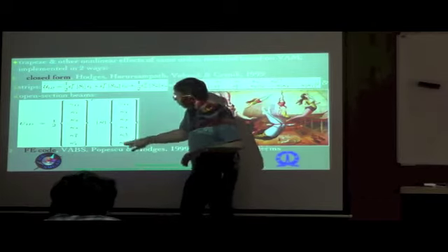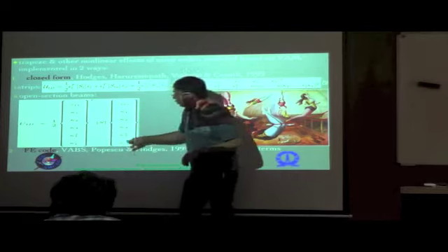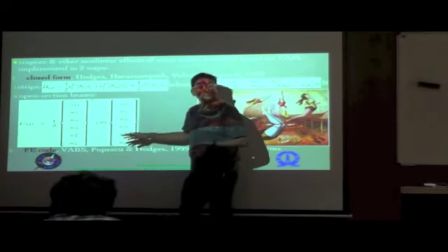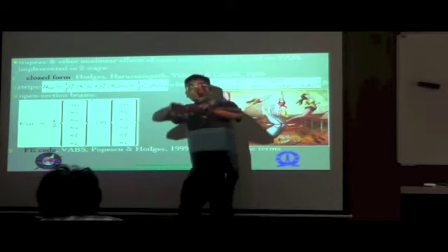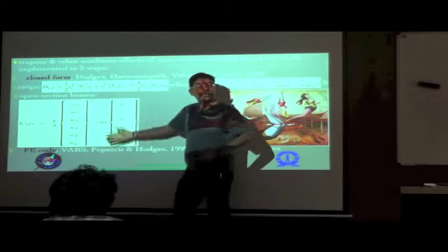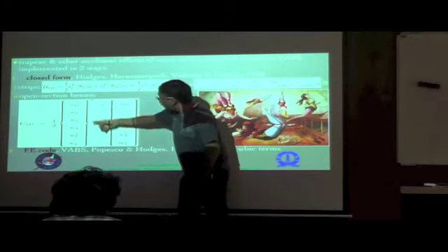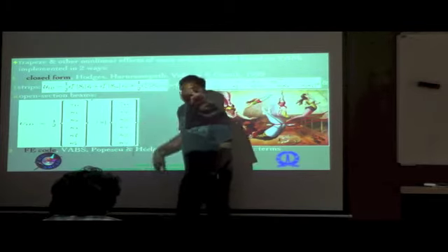So that's the reason why you see that there is an additional complication which results here, but this complication is something which makes life more difficult for the 1D analysis rather than for the cross-sectional analysis itself, where you basically have now this 6x6 matrix which is associated with the open sections.